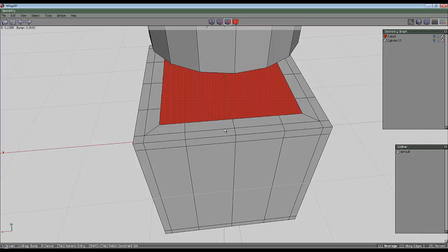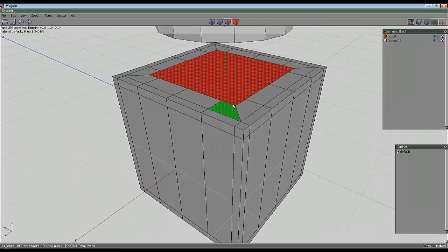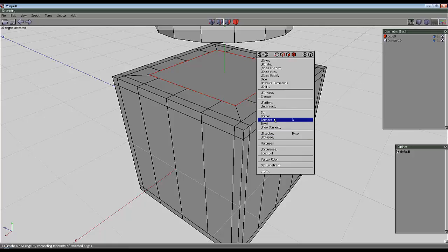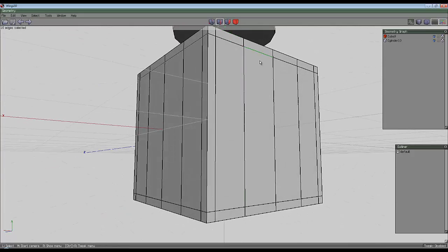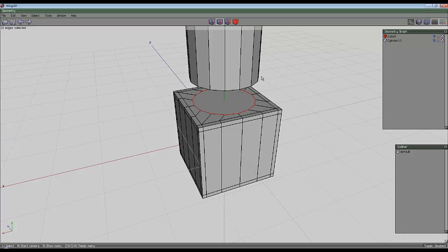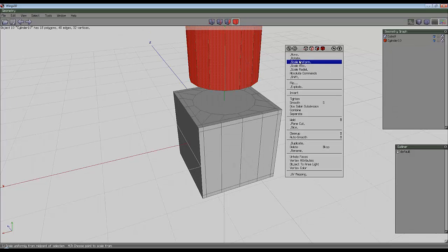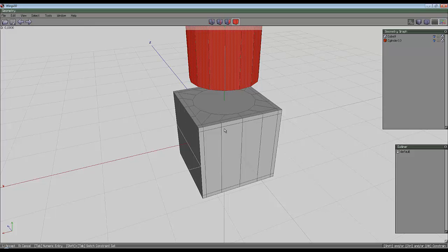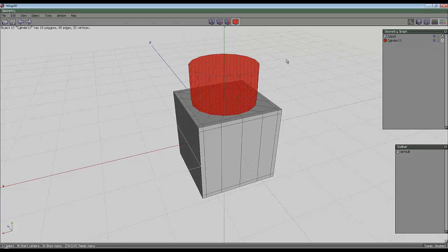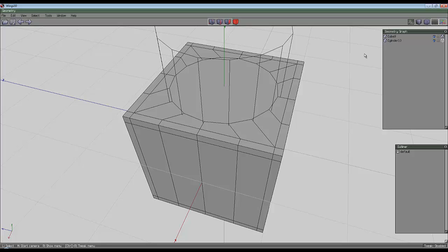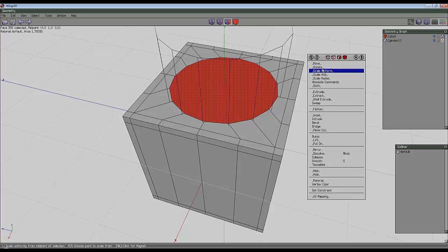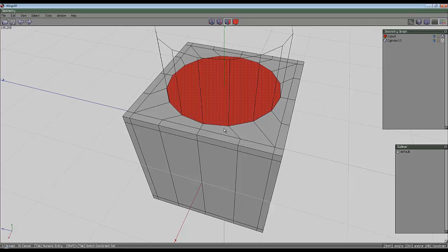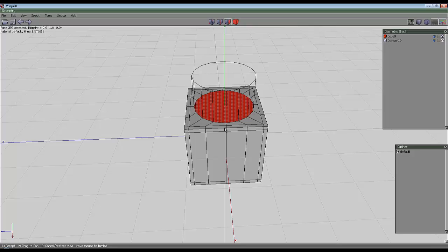So I inset it again. It doesn't really matter what size, because when I circularize it, like so, I can now determine the size of that circle. And I want that circle to be about the size of that circle there. So to achieve that, I'll move it on the y-axis into my shape, press W to select wireframe view, space to deselect, temporarily hide that, select this circle, unhide it, and then scale uniform till it's roughly the same size as that one.